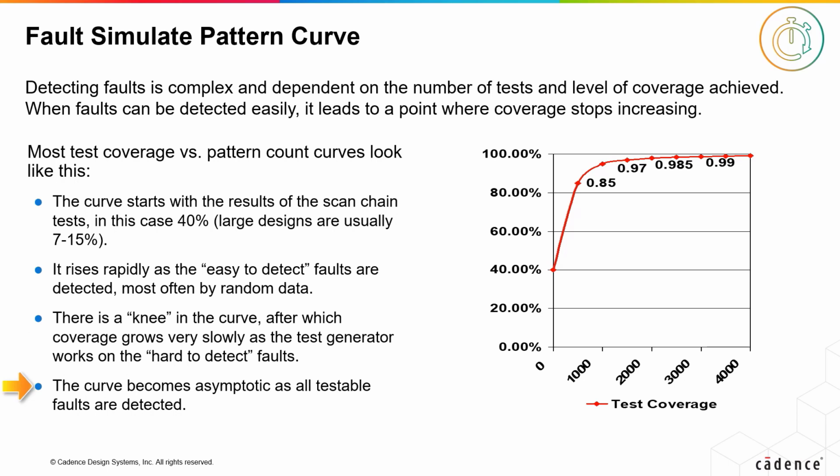The length and slope of the tail are heavily affected by a number of factors. One that is under the control of the chip design team is how well they have followed the design rules. Compliance with the design rules will often have significant impact on chip quality, manufacturing test cost, system test cost, field returns, and customer satisfaction. Conclusion.